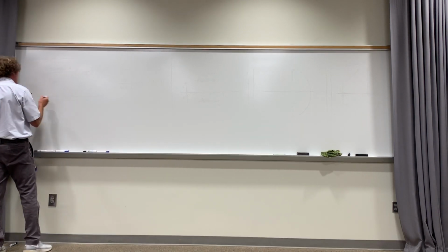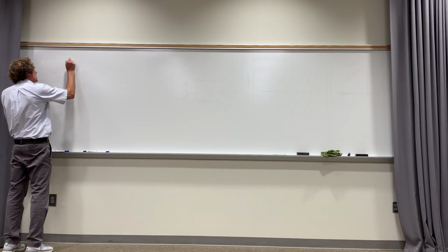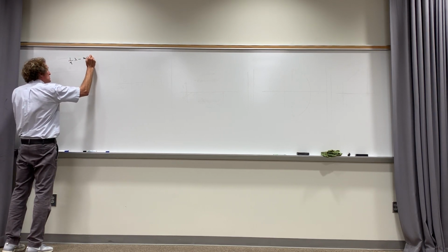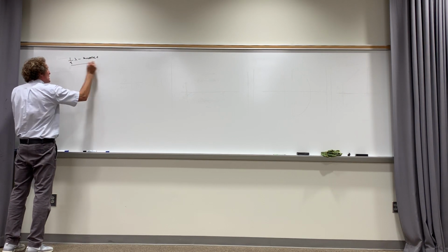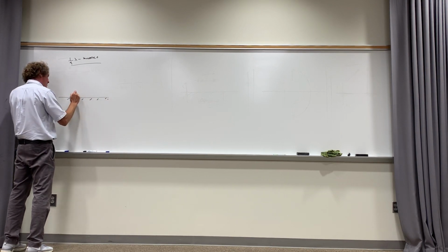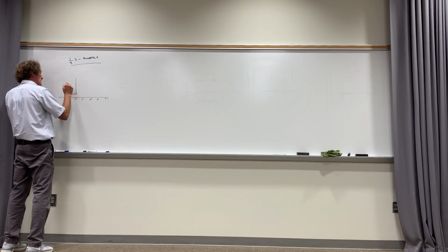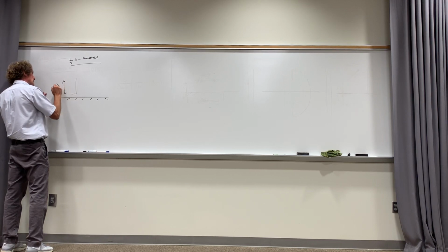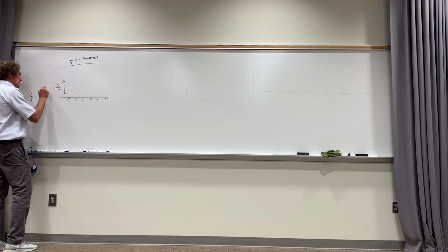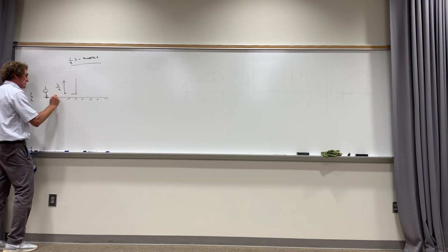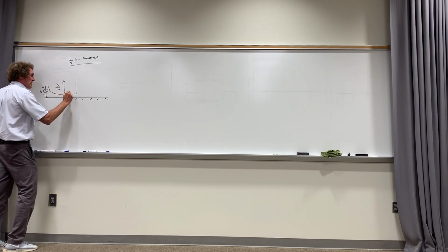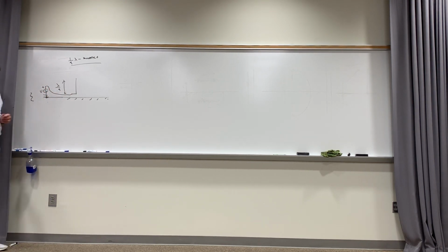So this is going to be the quarter wave monopole. First, put your ground plane down here. Above that ground plane, a short distance, I have an antenna that's lambda over 4 in length. The way I drive it, I take a voltage source, ground it, take the positive lead and feed it right there, and ground the other.